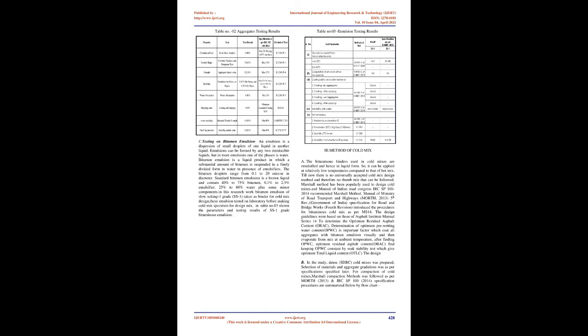Though performance-wise this has been the most suitable for pavement structures, its high use has several drawbacks like environmental degradation, high energy consumption, increase in carbon footprint, low output for mix production, low laying work in rains and cold weather, limited construction period in a year, oxidant hardening of binder, and health and safety hazard to labor.